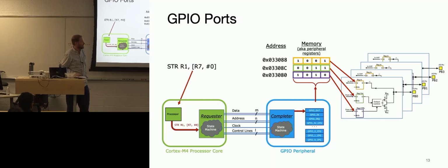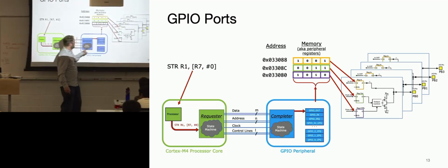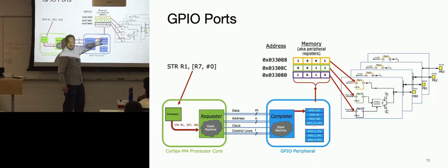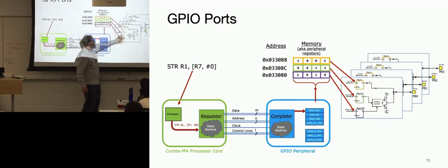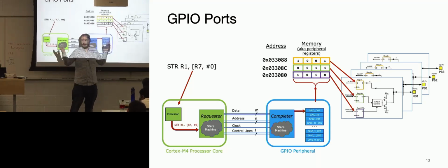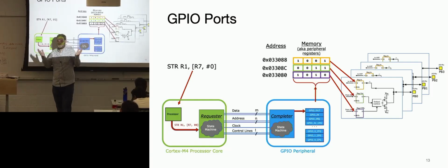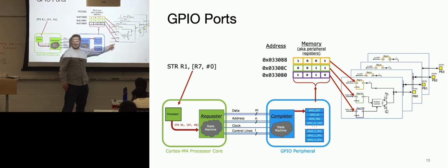What kind of memory is the GPIO peripheral relating to? Are those just flip-flops? Yeah. Yep. You wouldn't want to use SRAM, it's too dense, it's not the right structure, so almost all the time in the peripheral it's just going to be a flip-flop. Now it is up to the hardware designer, I don't know, they could use JK flops, but generally it's just going to be a D flip-flop.